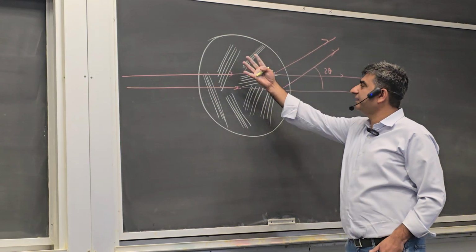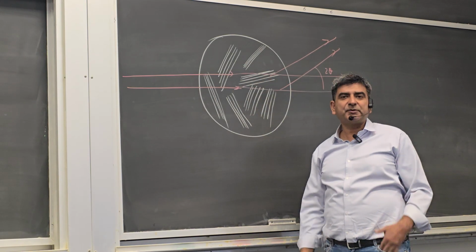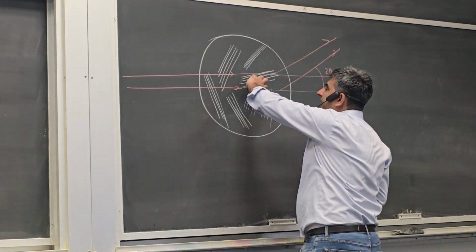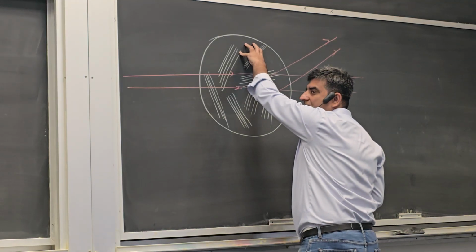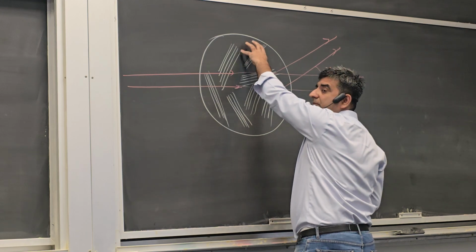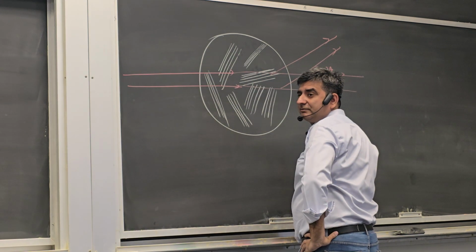Because it's polycrystalline, different orientations are possible. It's possible that in a different grain, in a different region, where there is a different orientation of planes, you come across a set of planes with a particular HKL index for which this condition is satisfied.